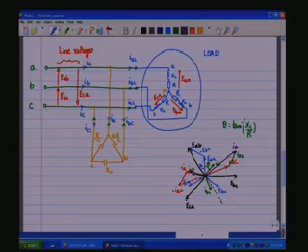So, we invert the direction of the currents there, and the resultant IA here is now leading the voltages rather than lagging the voltages, which would have been the case if it had been only the RL load.